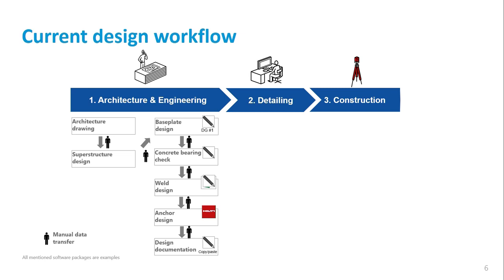So you need to do quite some checks. You need to size the base plate. You can do this probably via Design Guide 1 or whatever. You need to design your anchors. Hopefully you're using our software for doing so, probably also competitor software. You need to design the concrete underneath the base plate. You need to design the weld. So there are a lot of different tasks.